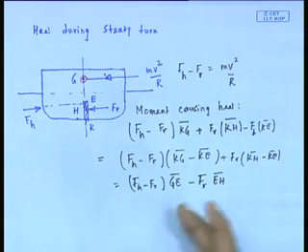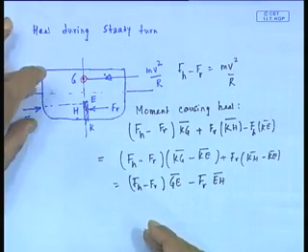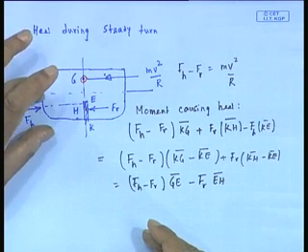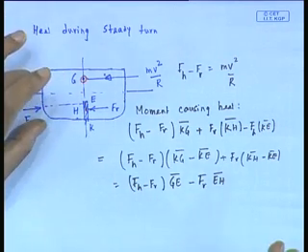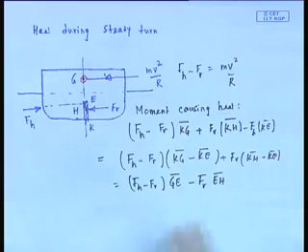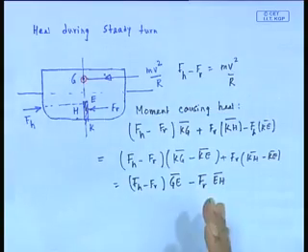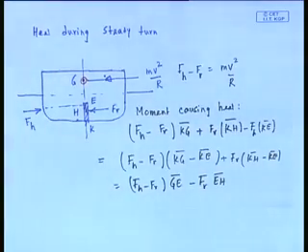Why? Because you remember that FH is expected to be acting approximately halfway through the draft, right? An approximate value we are talking. If you don't want approximation, you can always do the exact one. Rudder by choice, you normally have again almost like the draft. In fact, you will find the rudder area is slightly tapered upwards, so that the center of gravity is slightly above the midway, and so will be the pressure, because of the fuller form on the top.